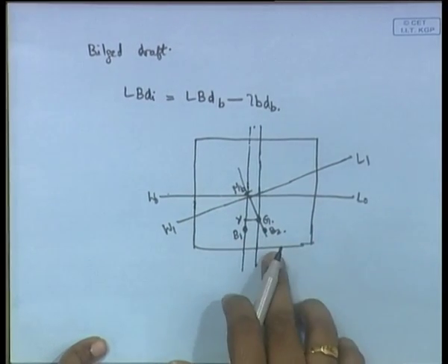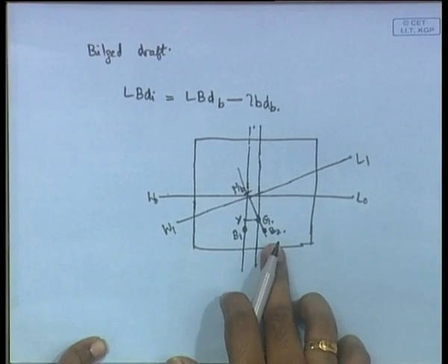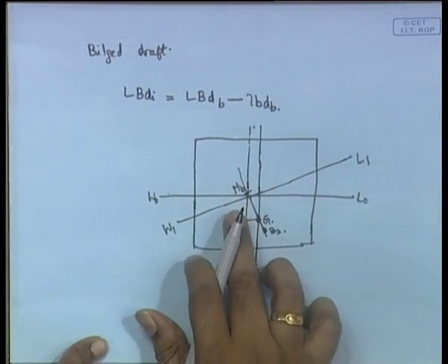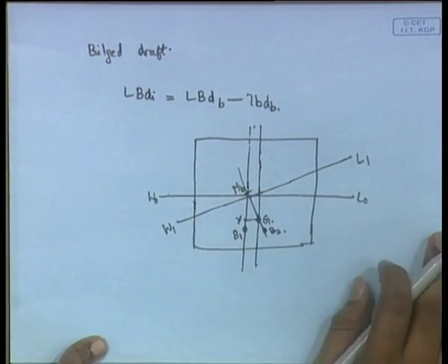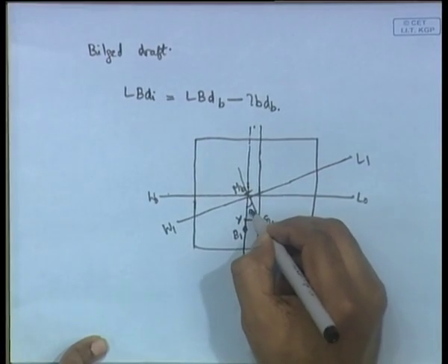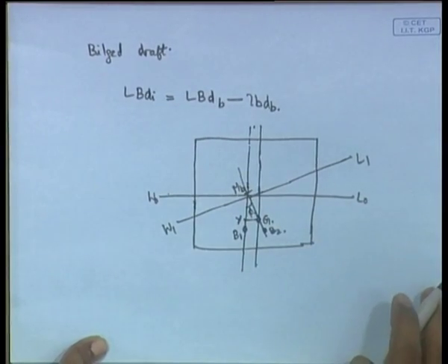Same thing, that is, the vertical drawn from B which passes through G crosses the initial vertical at the metacenter, that is what this is. So, this is the metacenter, that is MB, and the ship is heeled through an angle, let us say phi.